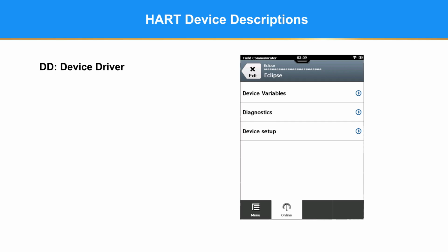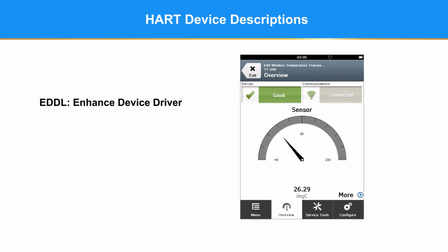It is a simple text-based interface. Customers demanded a more graphical user interface, so the HART Foundation published an Enhanced Device Driver Standard, or EDDL. This standard has built-in graphics, like gauges and status graphics. The manufacturer could select graphics out of a selection included in the standard. Some manufacturers provided drivers using the graphics available in the EDDL language. Most, including Det-Tronics, stayed with a text-based user interface.